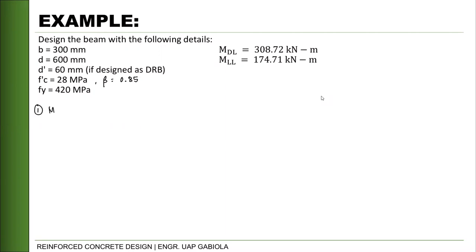Calculate for our moment. So, since moment na naman yung given, so that is just 1.2 Md plus 1.6 Ml. Okay, so 1.2 times 308.72 plus 1.6 times 174.71.